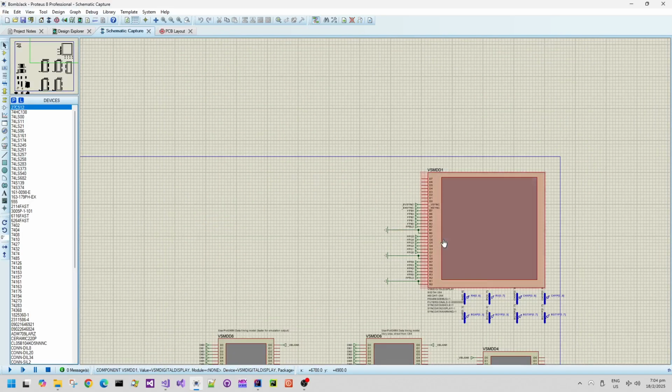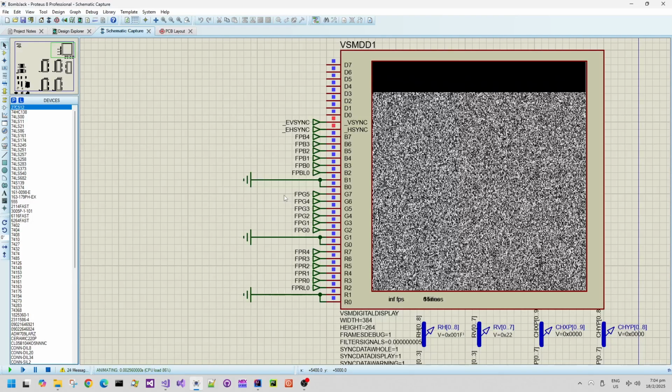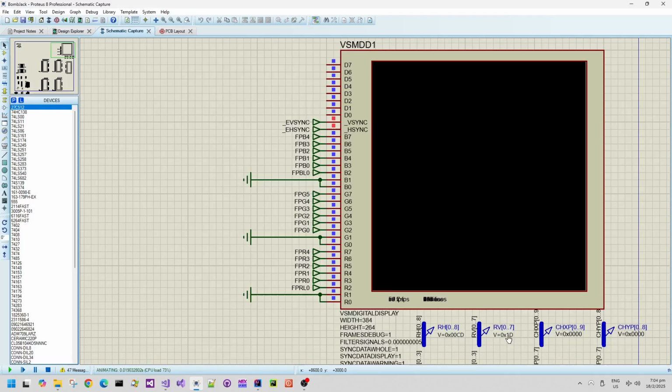double buffered. Now, I'm running this in this Proteus simulation, schematic capture, and also simulation and PCB layout design tool, and I'm running the simulation. Sometimes it takes a little while to start up. Here we go. So the black screen is expected, and that's because there are 2 double buffered frame buffers, initially cleared with effectively FF, which is all bits 1 in binary.